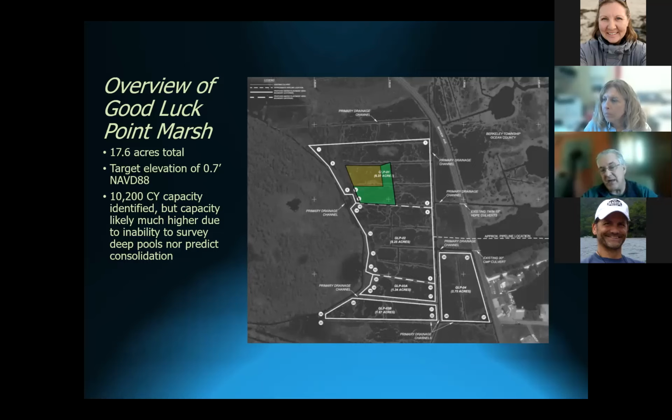So in some cases, I think the bottom line here is sort of think of this as a mud floor. You've got a lot of contours across the site. You've got deep places. Maybe there's some mosquito ditches, some drainage ditches, some salt pans. There's also high areas. There even might be areas that are man-made high. When the Mosquito Commission goes in and puts in ditches, they might be berms. So there's a lot of topography here. What we're seeking to create is a natural marsh ecosystem, which has natural marsh hydrology. So the idea here is to be able to go in and place material in a practical manner that will allow us to get to that target hydrology.